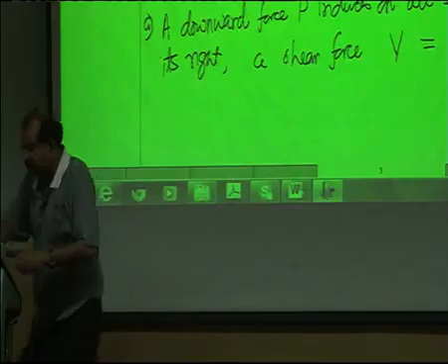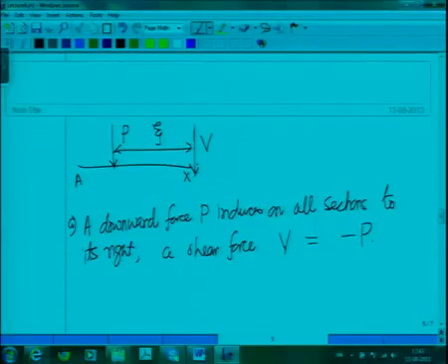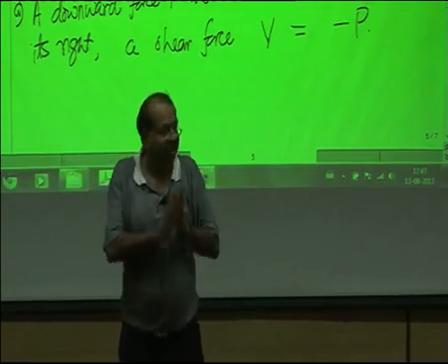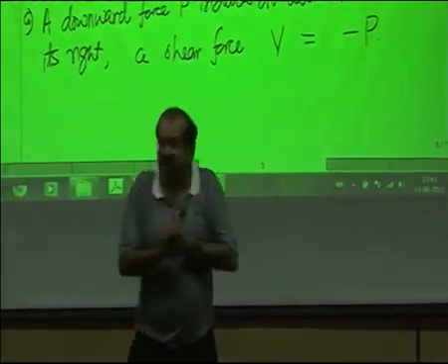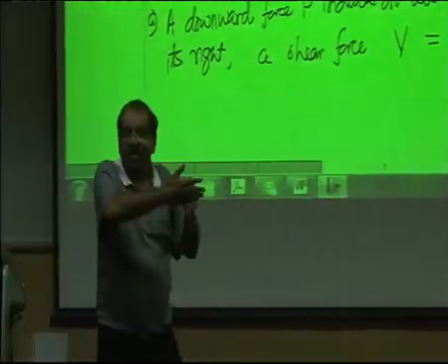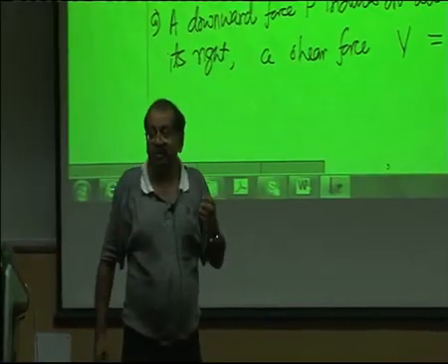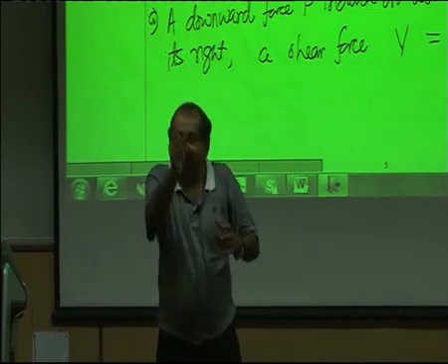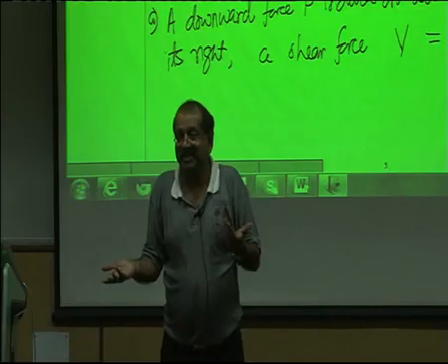So as you said, suppose there is a force AY acting at A, what will be its effect on V? It will produce a force equal to plus AY. So that means the net shear force V will be plus AY minus P. So instead of doing all the calculations, I will directly write this. I keep on adding all the forces algebraically, and that gives me the shear force. Is that clear? So this is if there are discrete forces. Now, as we had in a section, there was a distributed force. So for that distributed force, wherever I have cut it, I will find its equivalent and I will add that.